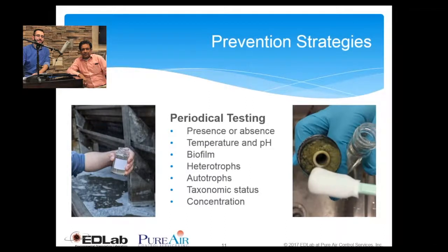Can you elaborate on the importance of periodical testing? Yes, this is another very significant step toward preventing Legionella: make sure that you have a routine checkup of the water. 2 or 3 things are very essential here. The water testing must be performed in order to understand whether Legionella is present or not. As I said earlier, monitor the temperature and pH to understand the suitability for growth.